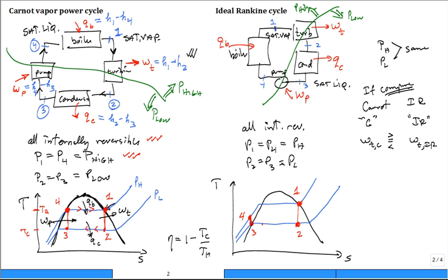And it shouldn't be a guessing game, right? We should know with confidence. And then guess what you do next, Professor? You go and you say, the heat rejected by the condenser, Carnot, the heat rejected by the condenser, ideal Rankine. Greater, equal, less. Then the work put into the pump in the Carnot, the work put into the pump, ideal Rankine. Greater, equal, less. Which one? Then the last one, the Q in the boiler for the Carnot. Greater, equal, less. Q boiler, ideal Rankine. Greater, equal, less. True?